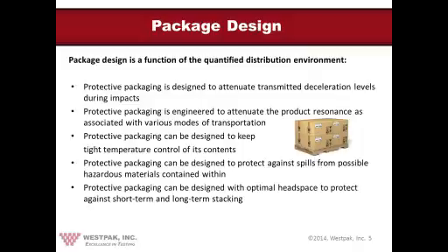We already talked about the hazmat on the previous slide, so let's look at stacking strength, which is another element that a protective package can protect against. Factors such as humidity, stacking patterns, dynamic forces, and time can degrade a box's stacking strength. A package has to be designed with enough safety factors to account for these. Also, depending on what's being packaged, the product can play a key role in offering optimal stack strength performance and it may be able to take some of the load from the packaging itself, so you can use less packaging material with the help of the product.